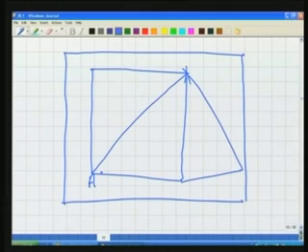So, what you have done, just by the measurement of these lengths there in the field, you are able to draw this skeleton onto the sheet. Okay. So, the skeleton of the ground is here on the sheet, on the map. So, what we learn from this? We learn one principle here, that is establishing control network. Okay.